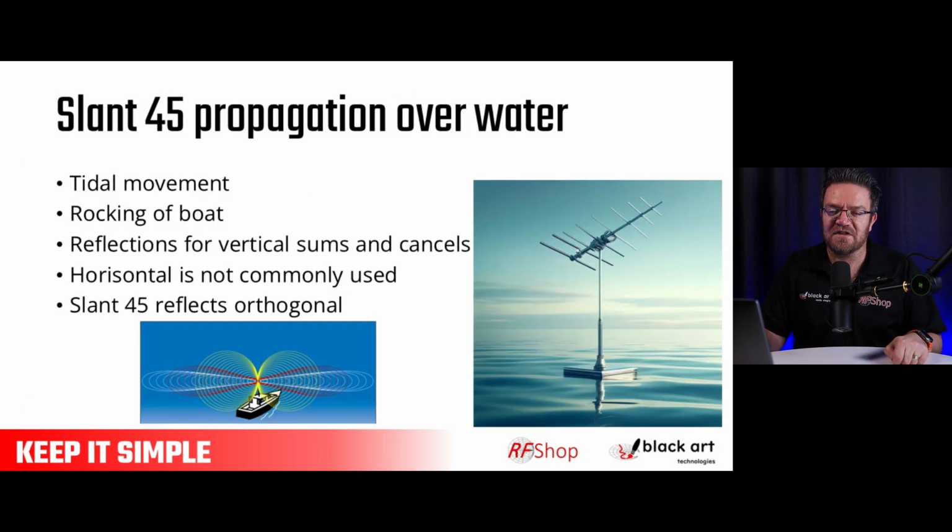Another trick with polarization is just on water. It's a simple thing, but you need to know this, and you need to realize this before you can do something about this. So on water or any reflection, if you have a fixed station and a fixed station, and there's a body of water in between, let's say it is the ocean, for instance, you have tidal movement that continuously goes up and down. So your reflection between the two is continuously changing, and it is really happening in radio links. If there is no protection, if there's nothing against this, twice a day as the water tide goes up and down, you will get a complete and utter cancellation of your signal. And that is a huge, huge problem.